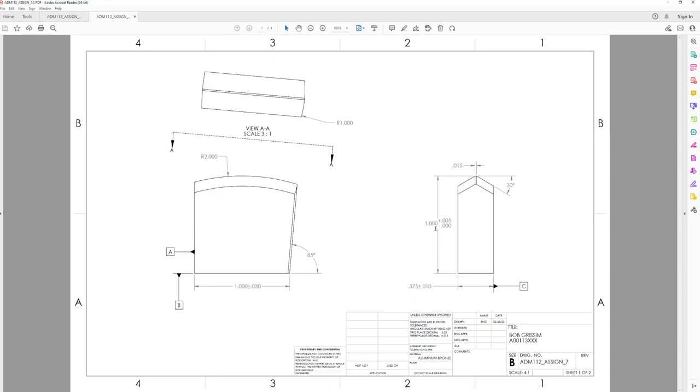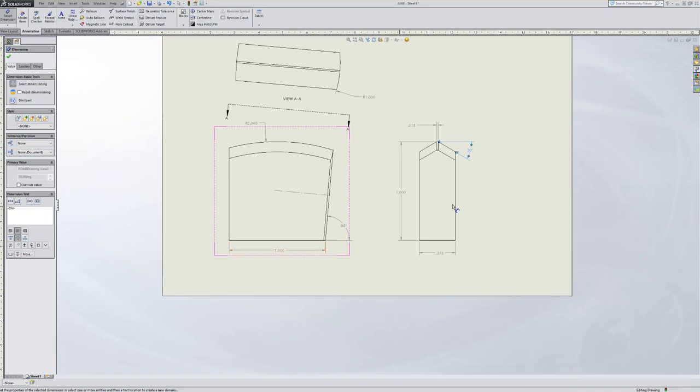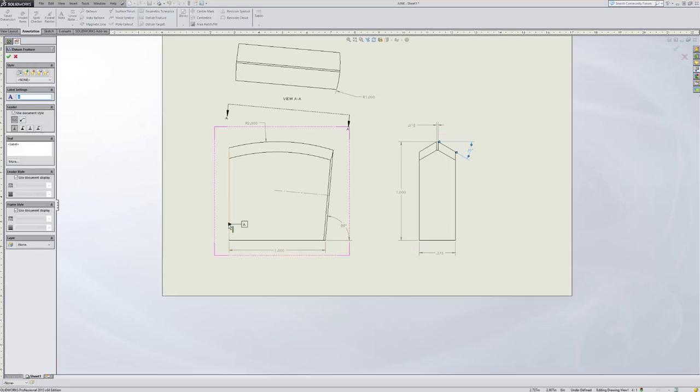We're going to come back in, and you're going to have some other items that you're going to need to do. Now, one thing that we haven't looked at before are going to be these datum feature planes, or datum features, or references. So come back in here to our drawing. We're going to come up and select a datum feature. I want to pick this edge for A. I think that's what it was. And then I want this to be B. So I'll pull it out here.